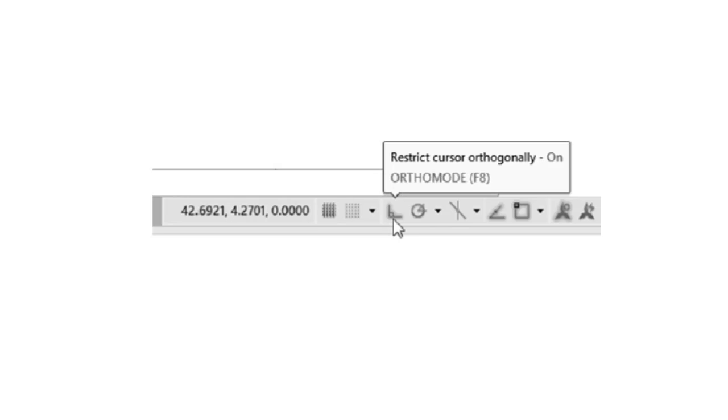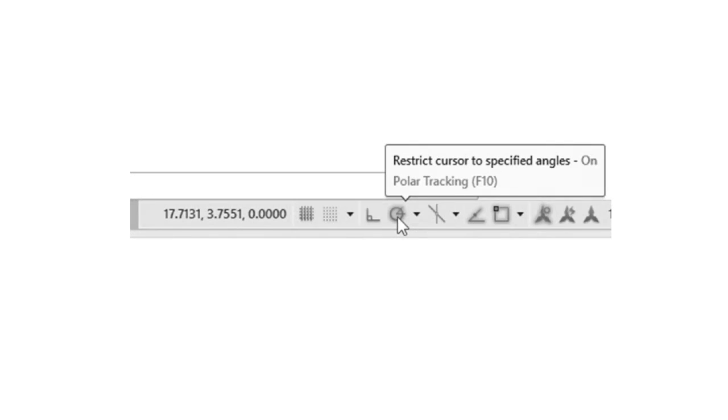Four, continue with the Line command. Move the cursor to a point below and to the right of the first point you selected and click again. You've just drawn a line segment, and a second rubber banded line appears.